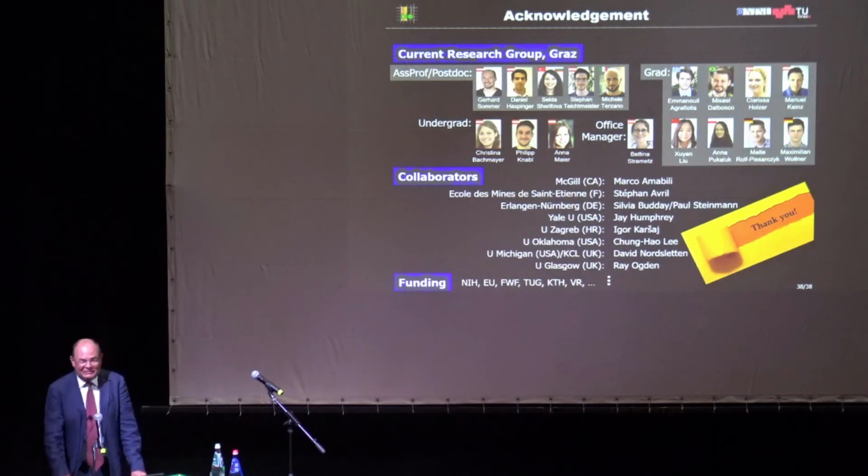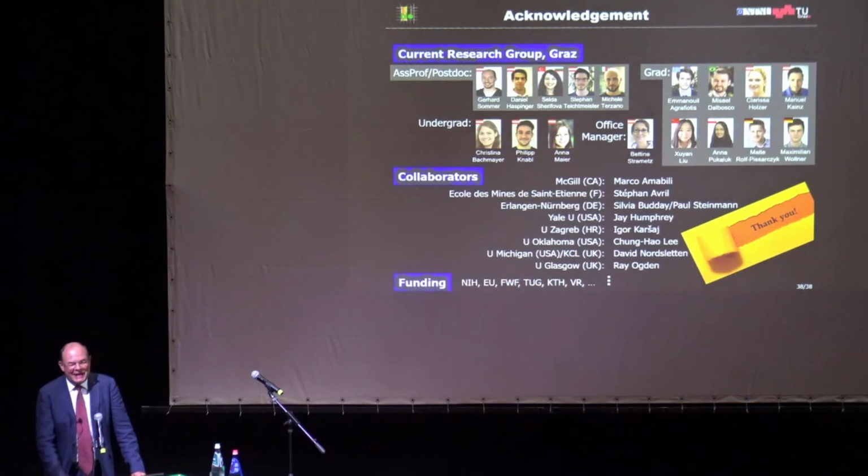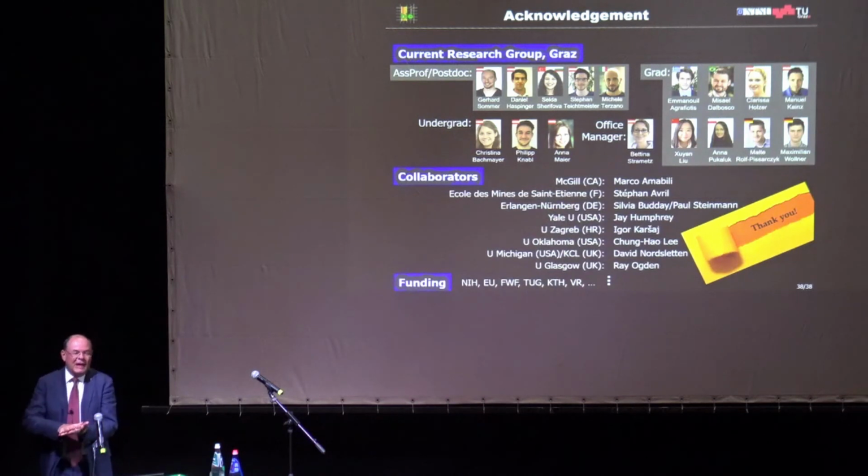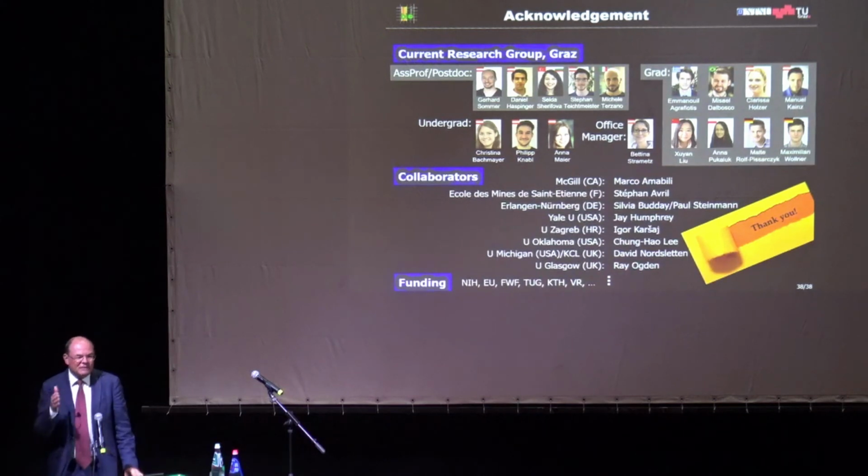No, this is a composite material, per definition. You have fibers which are embedded in this matrix material. Now the question comes, what is the interaction between these collagen fibers and the matrix material? The answer is, we don't know. We don't know this law of this interaction. And then also the smooth muscle cells are embedded, and this microstructure is very well known.